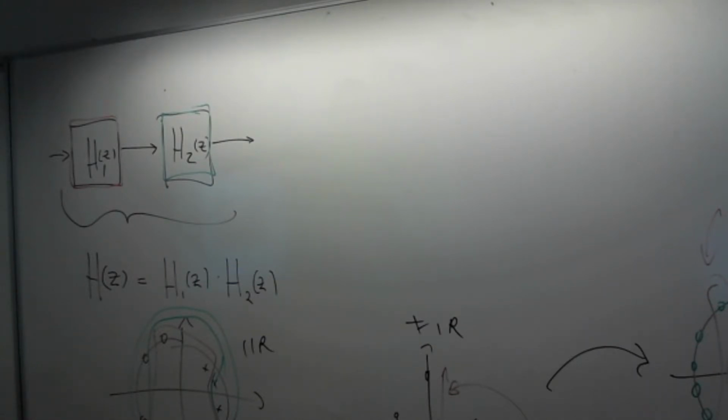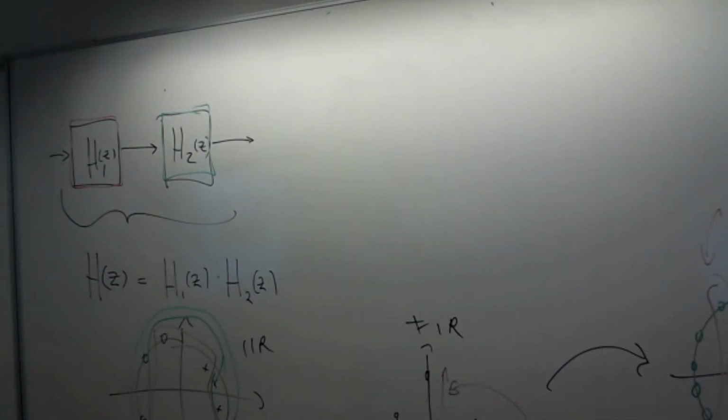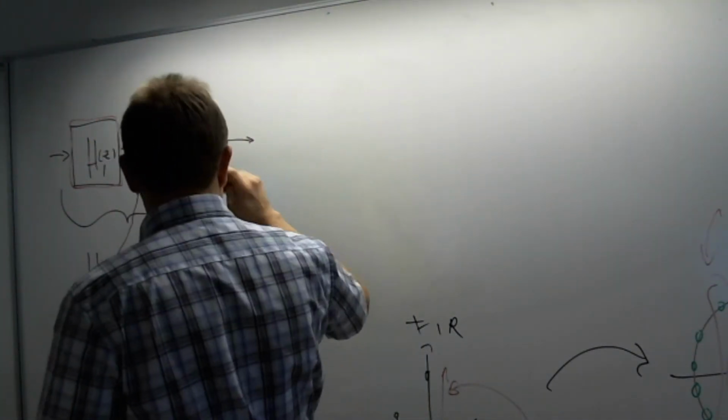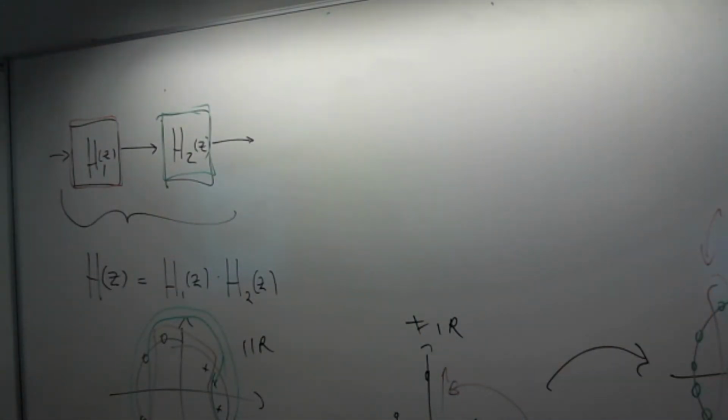So does it mean that you can use fewer coefficients for the second order to get it good enough? Yes. For that reason, you don't have to have such a long filter. If you have a really long filter, your coefficients are going smaller at the edge of it. Exactly. So you have shorter filters, but more filters, cascaded. And each of the filters is already pretty accurate, because the rounding errors don't add up that way. On cascaded, more or less they're suppressing each other.